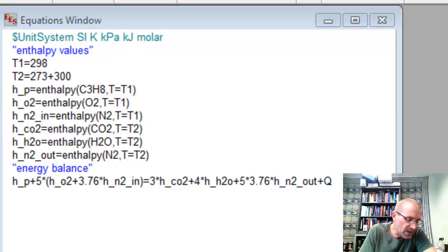I went ahead and found all of my enthalpy values using the enthalpy function. The enthalpy function, as I've written here in EES, is all three of those components, HF plus H minus H0. It's pretty simple to do in EES. You just call it with the enthalpy function. To get ideal properties, make sure you use the chemical formula in each one of these. Don't write out the words. Otherwise, you'd be getting ideal gas properties, and it would require pressure for the enthalpy value.